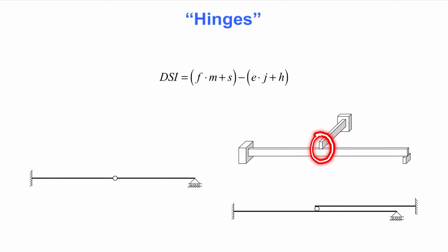Perhaps there are no nails or screws or any proper connection at this point, so that it is only the shear force in the upper beam that transfers into the lower beam. That means that bending moments, etc., are released at this location. In other words, this would be a situation where H is 5, because only one of the 6 internal forces transfers from one member to another.